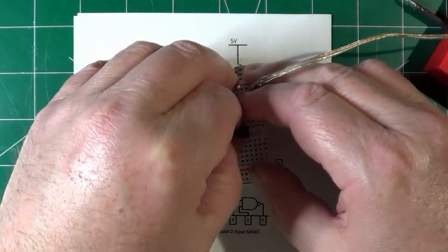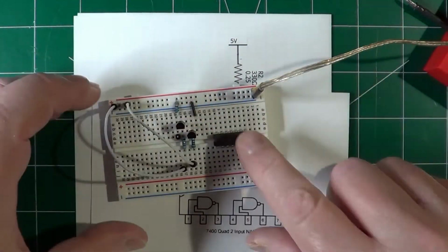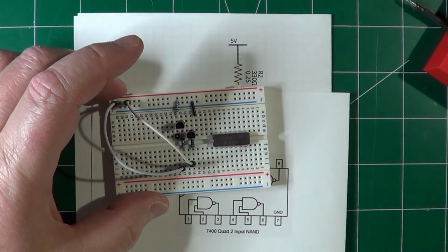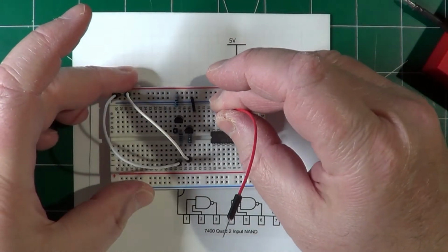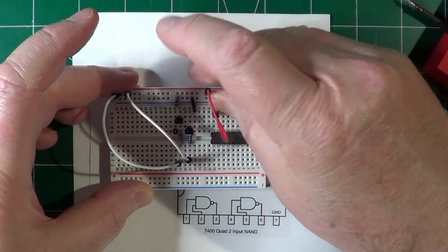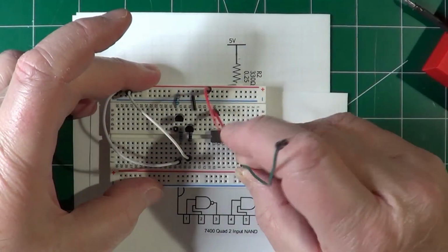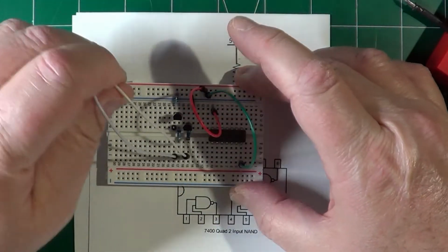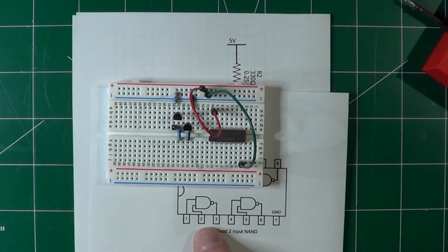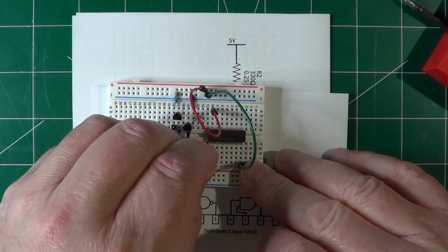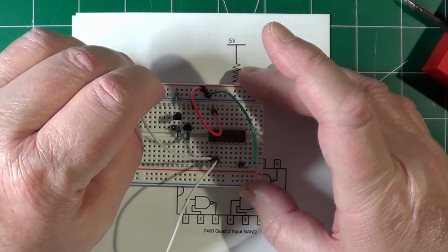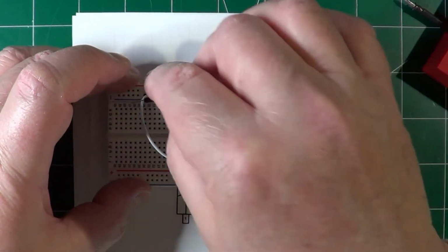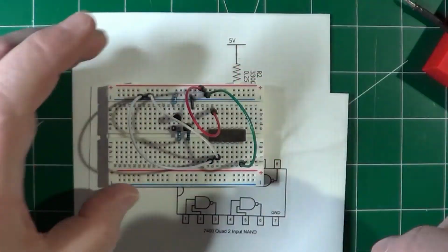Let's put it on the board so we can test it too. And let's temporarily disconnect the power supply and make the connections on the chip. So, pin 14 goes to plus VCC, and pin 7 goes to ground. I'm going to take now these two wires and use them as the inputs for this new circuit. I'm going to use the first gate of the IC, which has the inputs on pins 1 and 2, which right now I am connecting to ground.